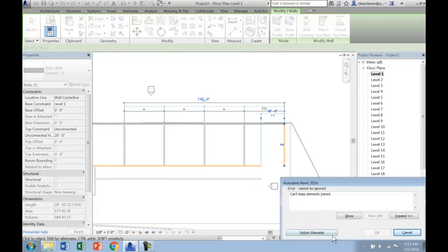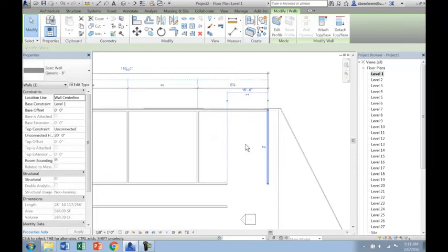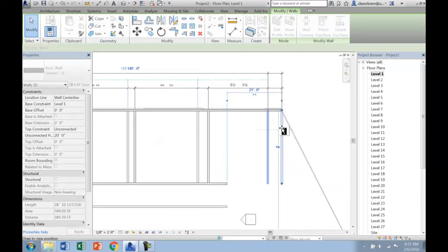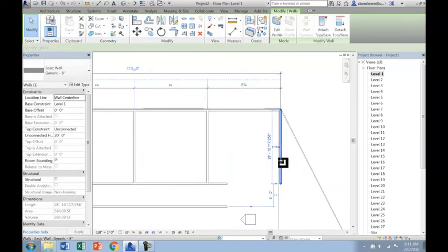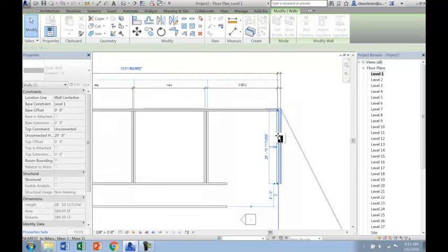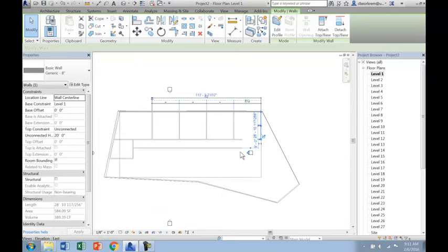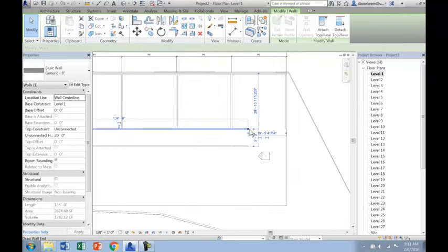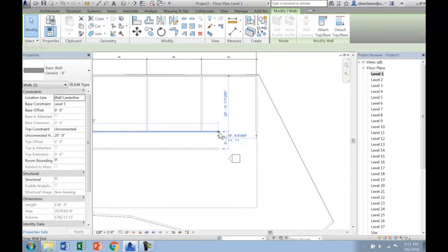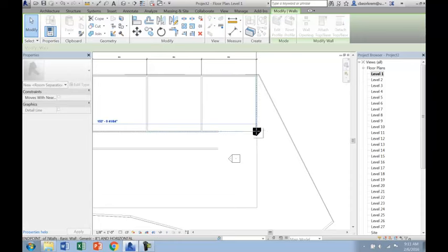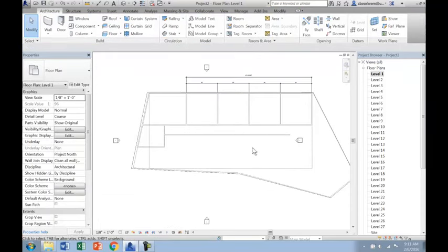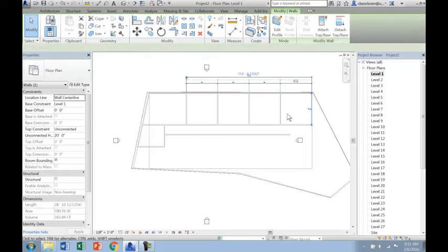You can see how this wall here that it had joined became unjoined, and again I can just drag this out and all of the other walls are basically going to snap to it as I go. This is a little deceptive because I'm looking down through a 3-dimensional geometry. And then I can use the dot here at the end to drag the length of this wall to match. So I'm going to assume this is a long set of galleries going along that way. And then I'll go ahead and mirror these across the hallway.